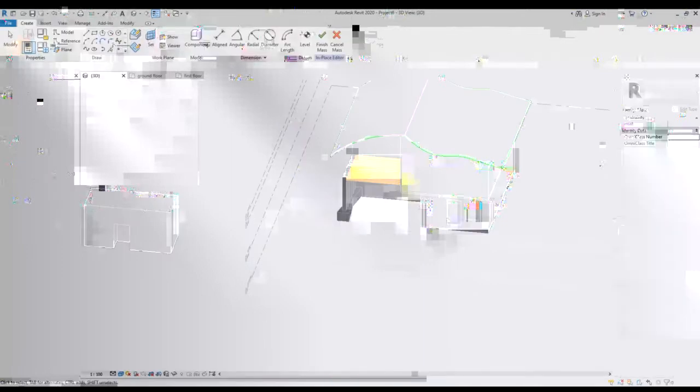So what we're going to do is go to place mass and start modeling. These are components that you will add to the building itself. So I'll click here on place mass and create a new mass. Let's go to the ground floor. I'll start creating shapes, and these shapes are supposed to be closed shapes. They cannot be open shapes.